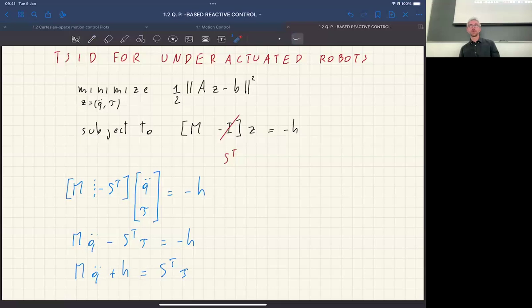And that's super powerful because if instead of using this optimization-based controller, we were using the classic control techniques that we discussed before, like operational space inverse dynamics, or all the other control methods for joint space control we have seen, it wouldn't be that simple to introduce underactuation, because we would need to redo all the math for deriving the closed form expressions of the controllers.